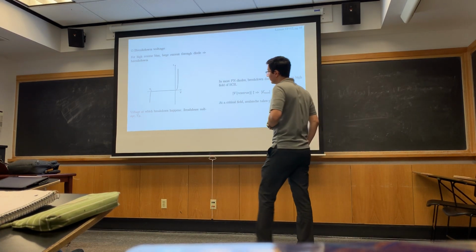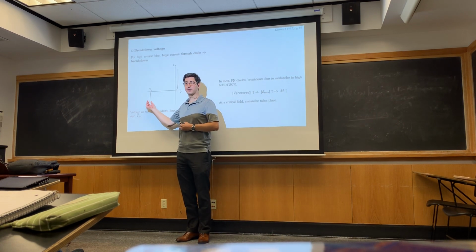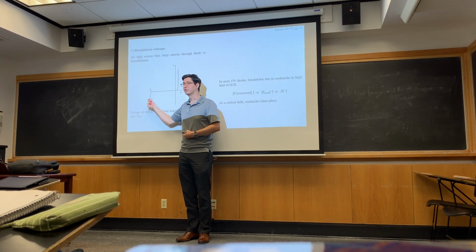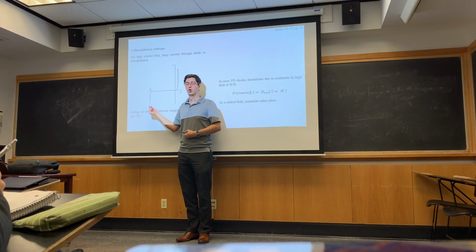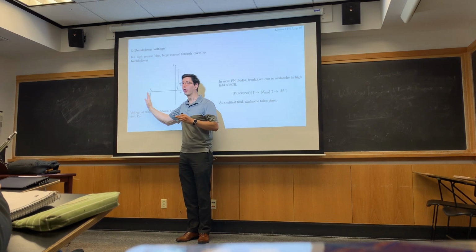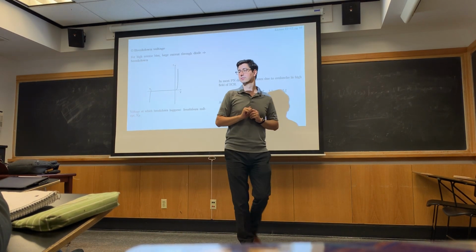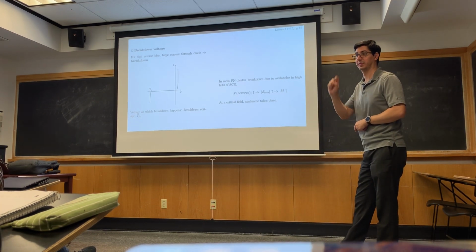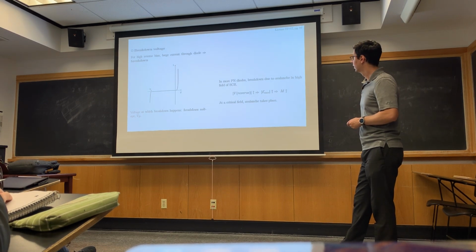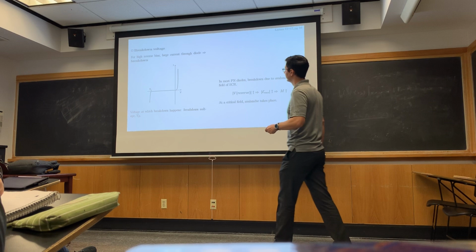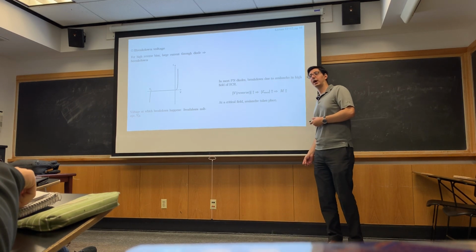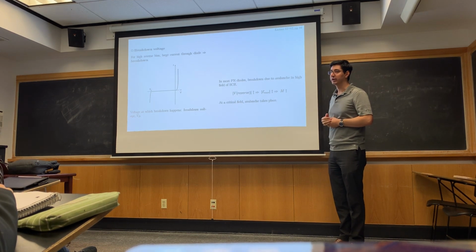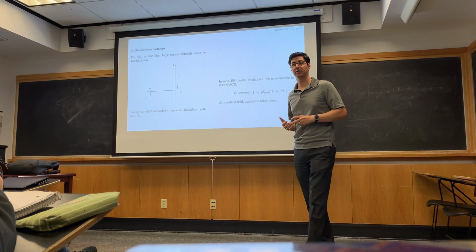So depending on your application, this can either be a parasitic effect or an advantageous effect. You can design your whole application around this, or you could design your whole application to avoid this region. Just depends what you're trying to do with your diode. A diode can do more than just one thing. Okay? So in most PN diodes, this breakdown region here is due to our favorite phenomenon, because it's the coolest phenomenon we can talk about. It's avalanche breakdown. Somebody remind me what avalanche breakdown is?